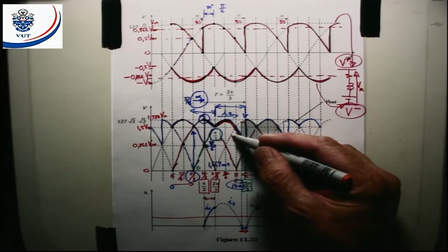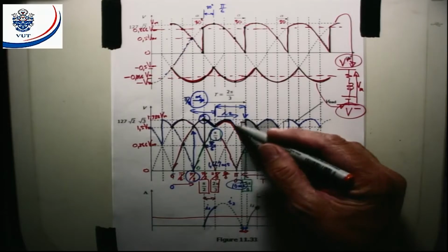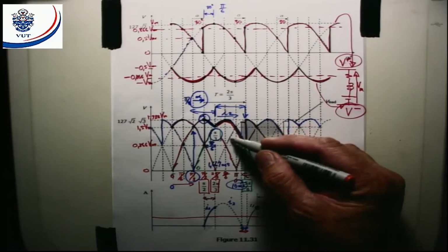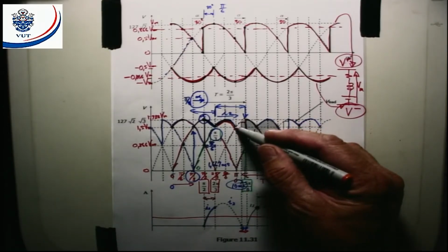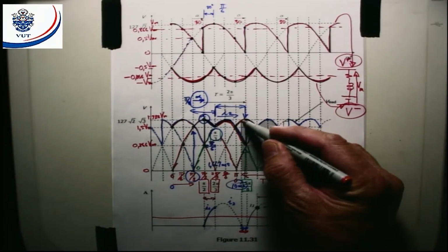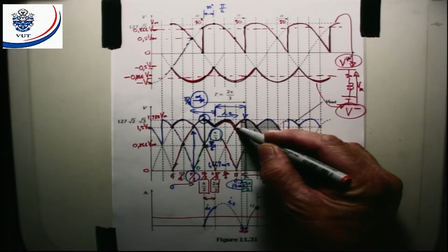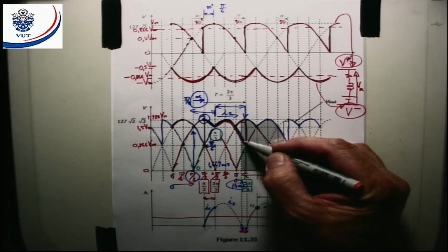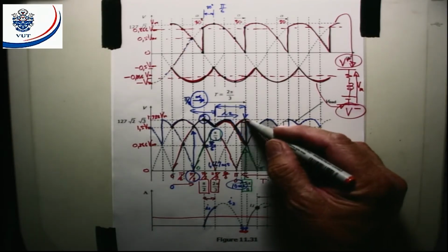That one is the one that I want to switch over to, but I can't switch over to it at that point there because the thyristor has not been switched on. If the delay angle was 0, it would switch on there and I would go up on that path there. But now I don't switch on. I wait 30 degrees, so I'm going to go down here and only then am I going to switch over.